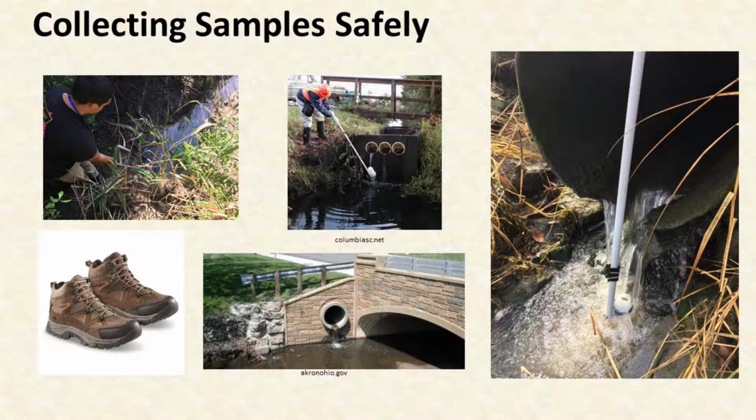In a scenario where an outfall is located on the side of a steep hill or a cement block, the sample pole would be used to lower the collection cup from above. This avoids the hazards posed by climbing down and back up a steep embankment or a wall.